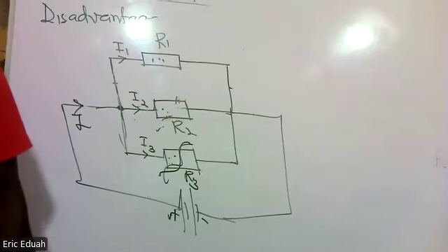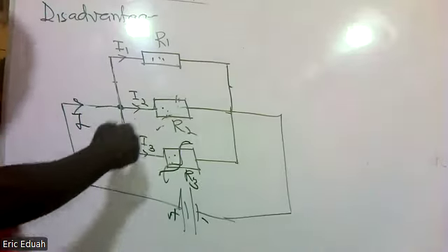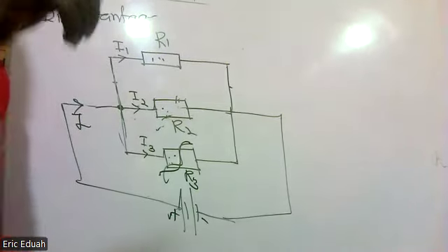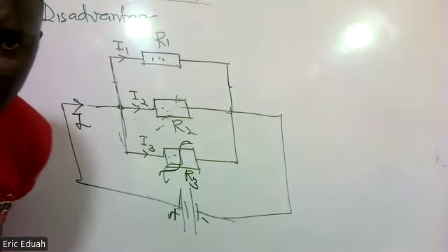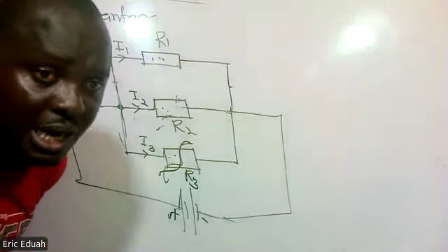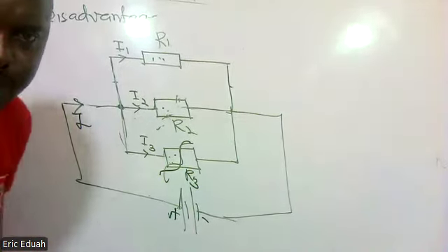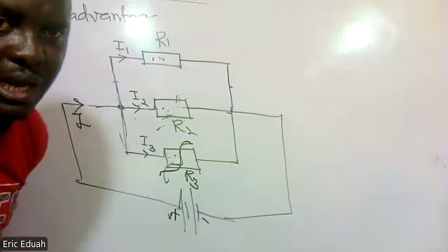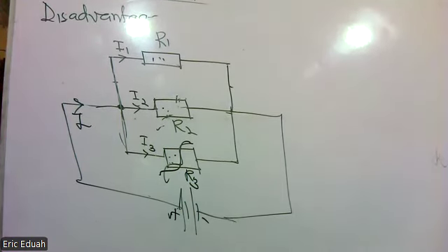Yes, please. So under this connection, a fault or problem with any one of the loads does not affect the other. So the sockets in our rooms, the modern arrangement or circuiting of sockets in our rooms is by a ring system. Ring system is this one. So that when there is a problem with one of them, it doesn't affect the other socket outlets. Okay. So here a fault with one of them does not affect the others.